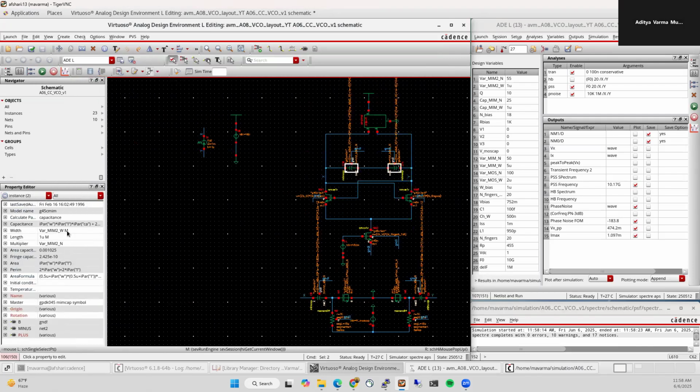So in this case, the width we chose was 1 micron and 55 multiplier factor. The layout becomes weird when you do that because it becomes too thin and then a lot of them. Instead, what we can do is make the length 5 microns, the width 1 micron, and the multiplier factor 50. Right, so it should be actually 11. So 11 times 5 is 55, which is what we had here. But I increased it a little bit because as we'll see, when you do the layouts, it will shift the actual capacitance value